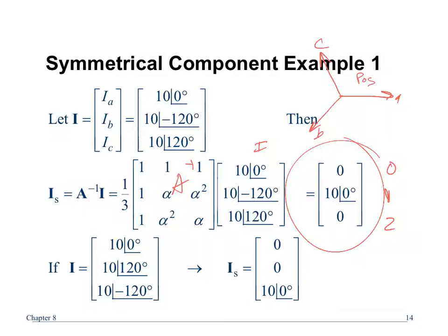What if you swapped, so over here, right, this is A, B, C. What if I swapped B and C? Now, this is B and this is C. What type of rotation is it experiencing? Is it perfectly balanced? So shouldn't I only get something in the negative sequence rotation land? Absolutely.